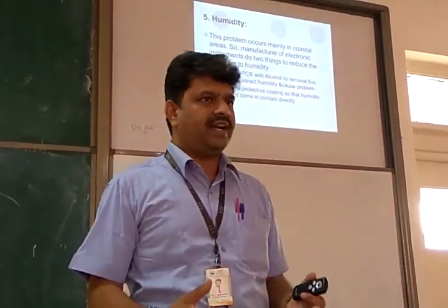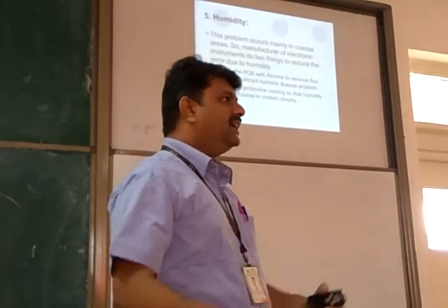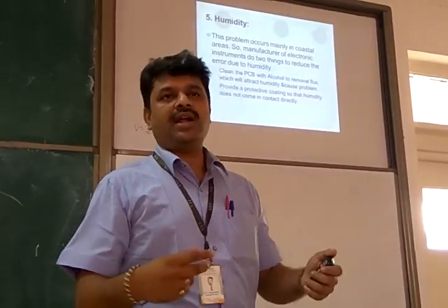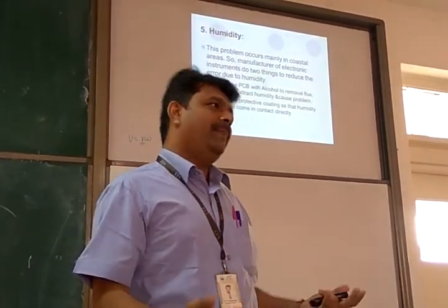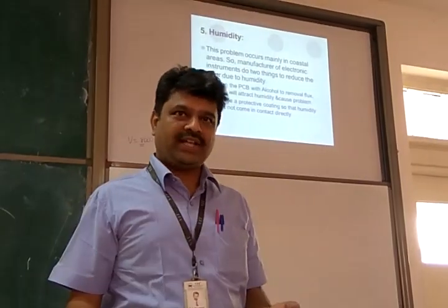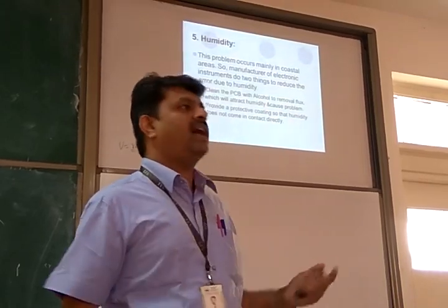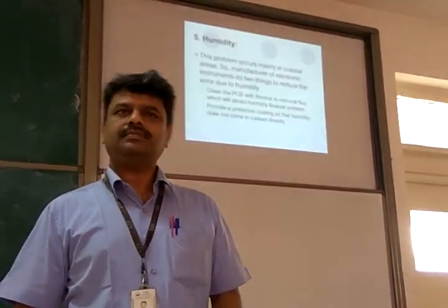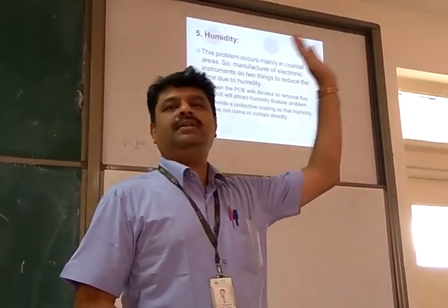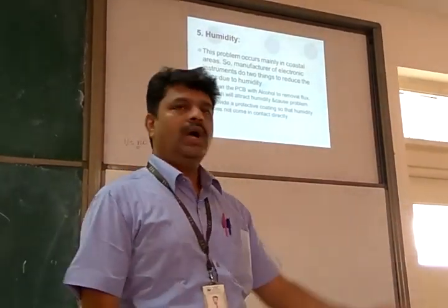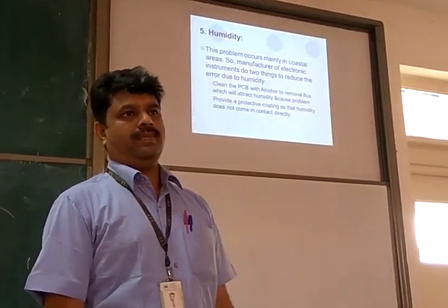When we investigated, all this problem came from the flux not being cleaned properly after the soldering process. So we started cleaning it. We take a brush, typically a toothbrush, though there are special brushes available. Wet it in alcohol and clean the PCB board after soldering to remove all the flux material. Dry it in the fan for just 10 to 20 seconds, and the alcohol will evaporate. Or you just send it through a heater on the conveyor, where it gets evaporated.